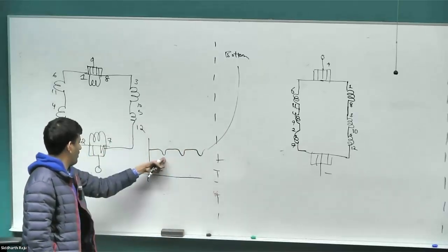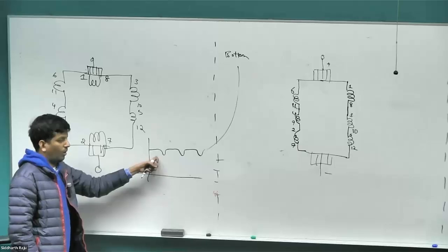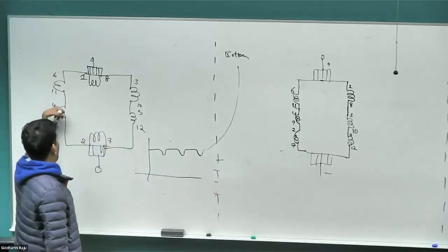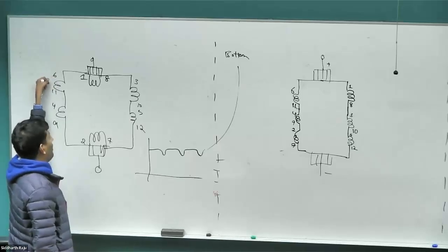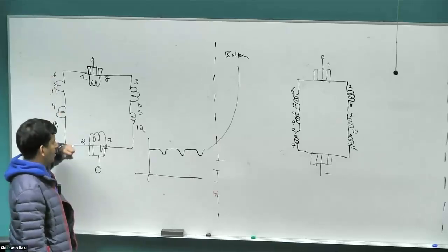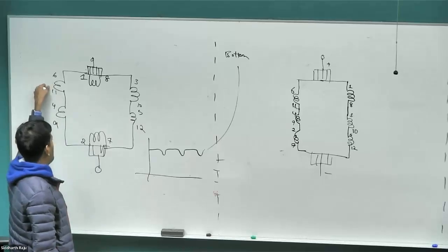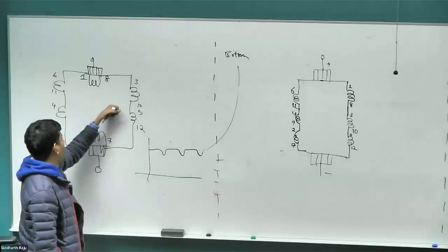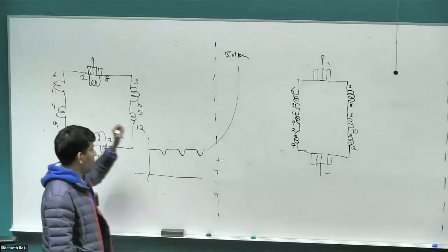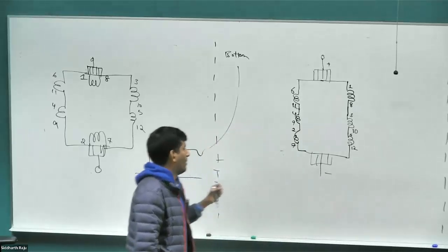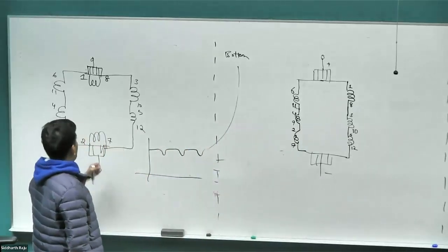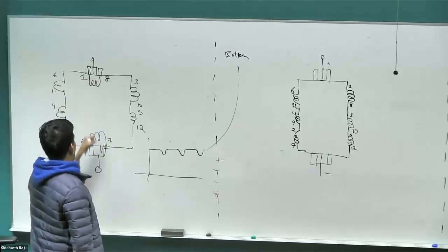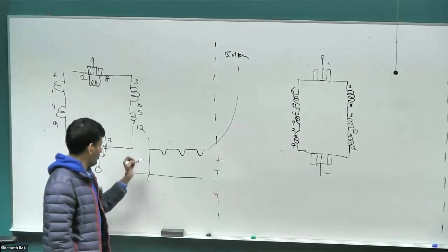Right? The tiny dip is because one set of coil is not producing EMF at this point. The rest of the whole batch is producing EMF. If you have, say, 12 slots in the motor, as we had in our rotor for our lab motor, you have 6 on one side and 6 on the other. Typically you would have 6 here, 6 here, but when the commutator action is acting, you would have 5 here, and then 1 and 1 on the top and the bottom being shorted. Right? So there will be only a tiny dip.